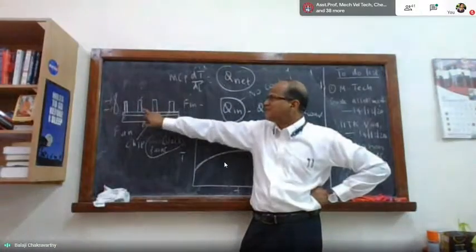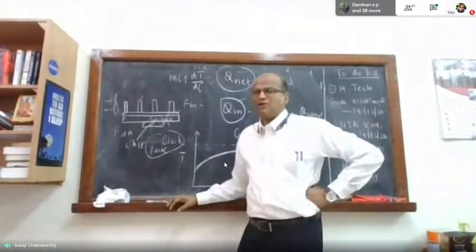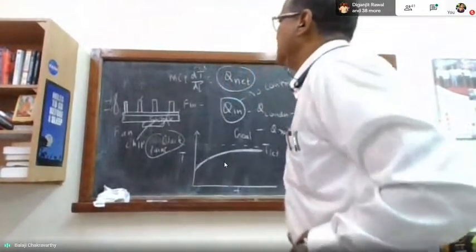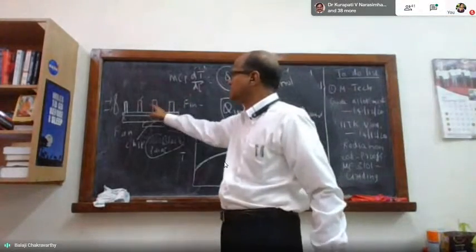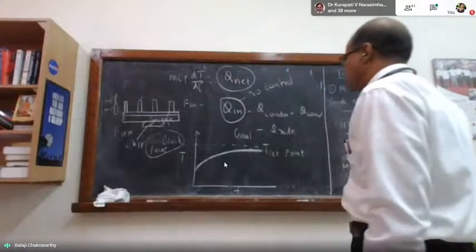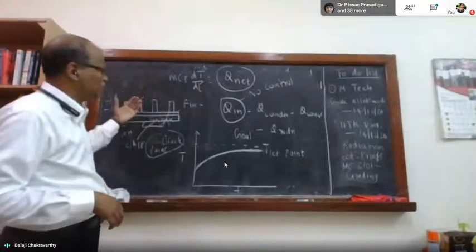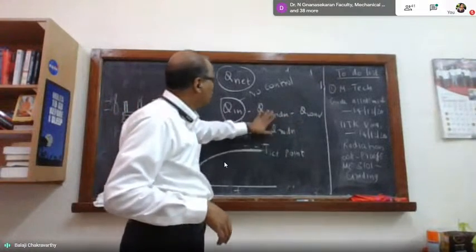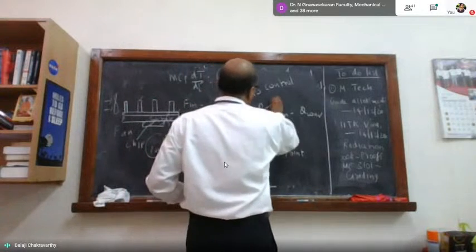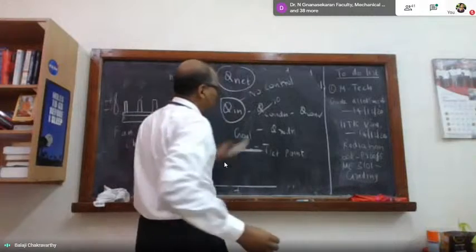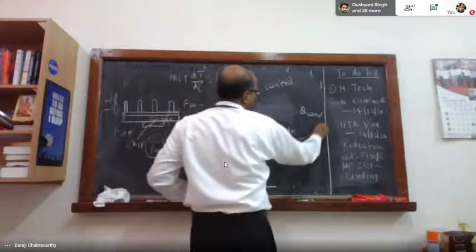In this case, the whole sink and the substrate and the chip are all assumed to be at one temperature. If they are not at one temperature, then you have to solve for conduction in X direction, Y direction, Z direction. For radiation, it's not so straightforward because the fins are seeing each other. So we use the view factor and so on. And if you are using some phase change material, or jet impingement cooling, the calculation of each of these quantities is going to be very tough for you. The calculation of this Q conduction usually may not be there in this case, because otherwise it has to come to the left hand side.